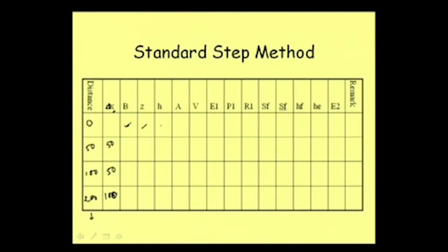Then suppose at the first point we know the H value, so that is known. For this known value we can calculate the area. Once we calculate the area, since we are doing it for a particular Q, the velocity is also known.